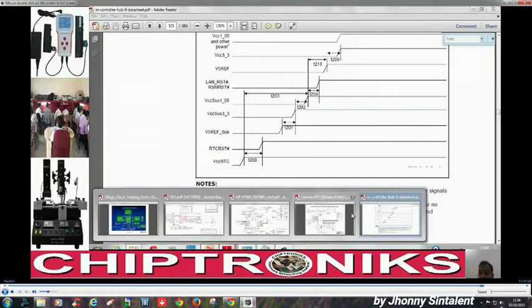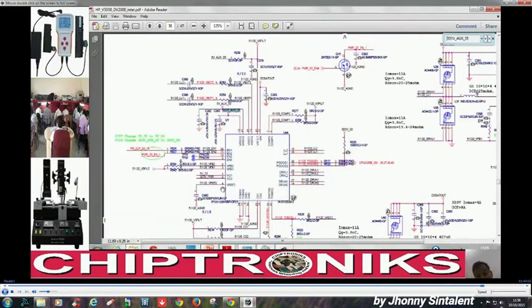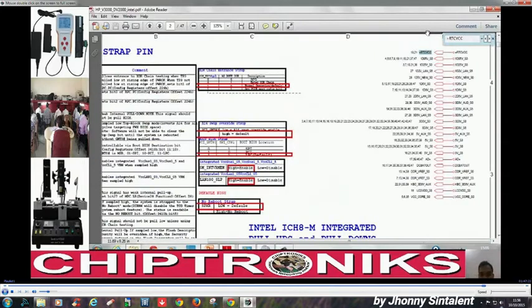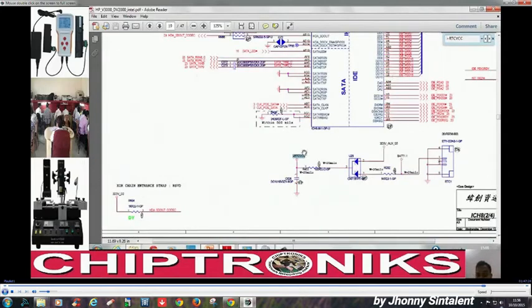While checking VCC RTC, we have come back to the 3 volt 5 volt regulator, but in between we had checked many things, like plus RTC VCC, and we find this is generated.